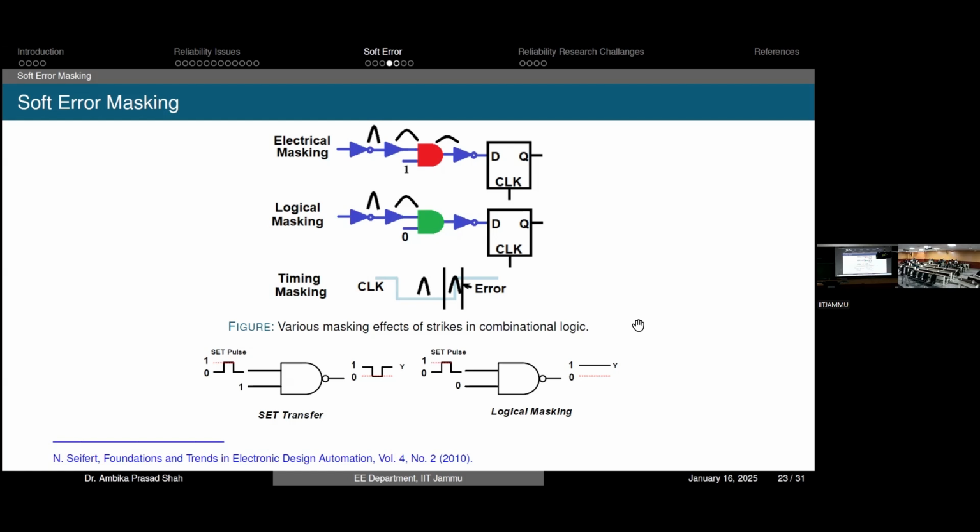Let us assume I have a D flip-flop, and let us assume this is an edge trigger, positive edge trigger. The symbol is not the positive edge trigger, but consider it is positive. Initially consider it is a level trigger. If it is a level trigger, then what will happen? Let us assume this is a positive level trigger. Whenever the clock signal is positive, then during the entire period of that positive clock pulse, if some impulse is coming, this will be transferred to the D flip-flop.